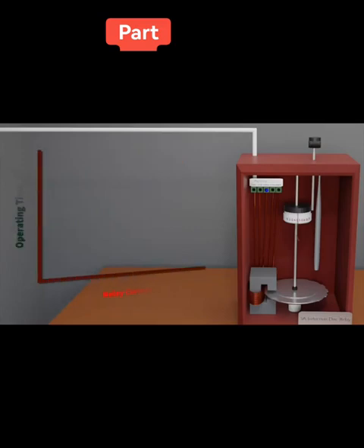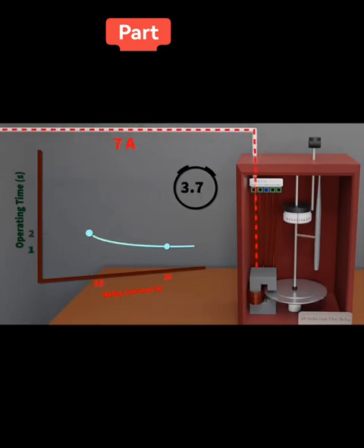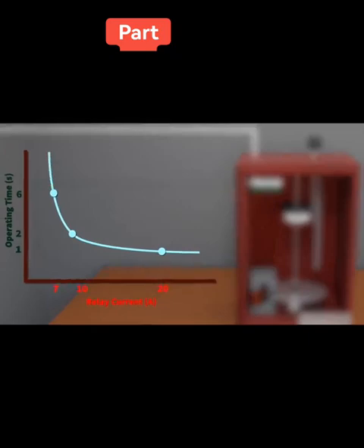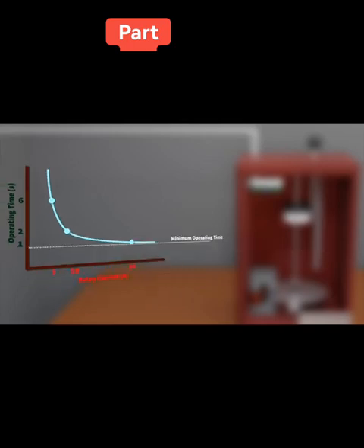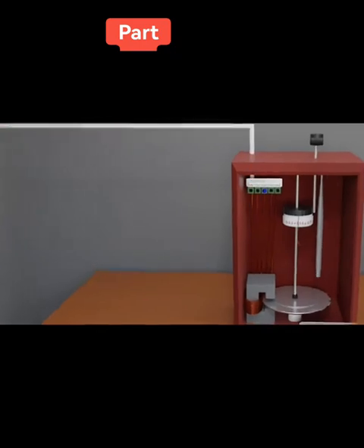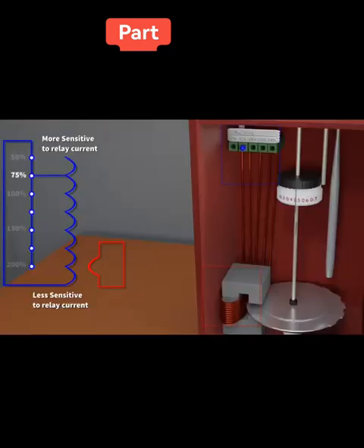It's like replacing a breaker in a substation. You cannot replace a breaker just because it has the same voltage range. You need to check your operating time. So this is an indication, there is a time tripping curve, all right? So look at your graph. If you have 20 amps, your minimum operating time will be about 1 second. So it means it will trip faster the higher your fault current, right? So you have to configure this due to a tripping time before you burn things.